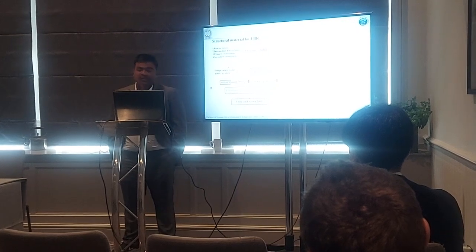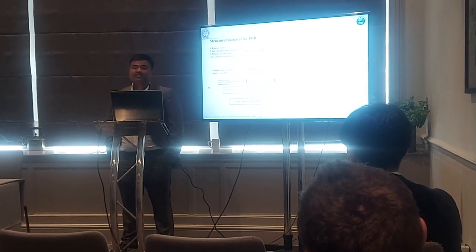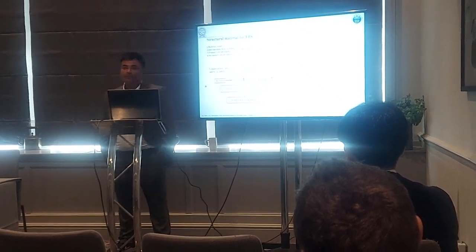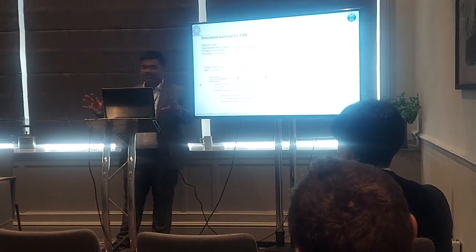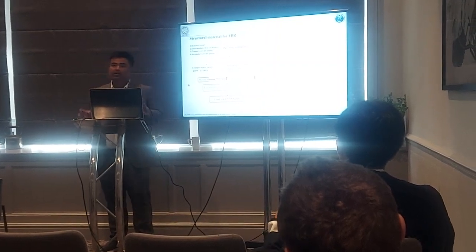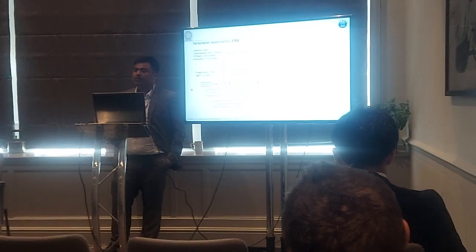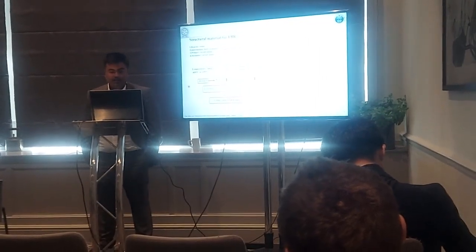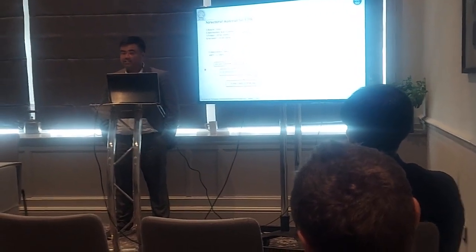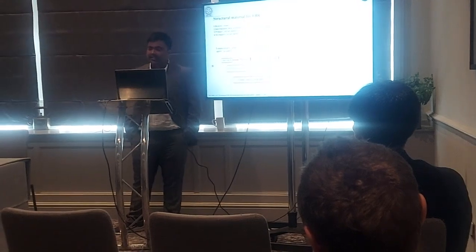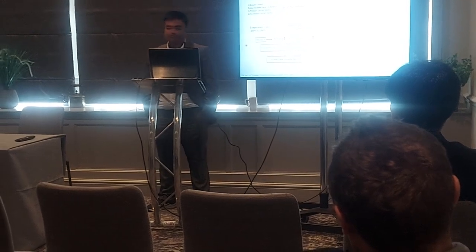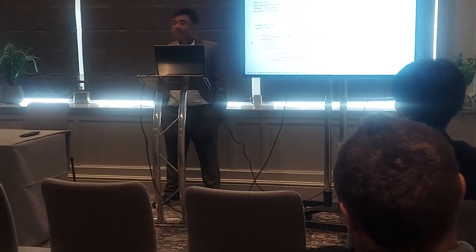In the SS316 LN India is using, the carbon percentage is 0.027 and the nitrogen percentage is about 0.07. This addresses the problem of sensitization. Actually, in normal SS316L, it is reduced by introducing nitrogen. By increasing the nitrogen, the stacking fault energy decreases and the stacking fault size increases, making cross slip very difficult. So it helps to strengthen the material at high temperature. So life prediction is important.